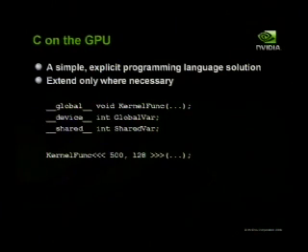As well as running, can you copy between the local memories? No, so the collection of threads that share the on-chip memory are resident in the machine at the same time, but they're not allowed to communicate with others. So we still restrict you on that sort of thread block granularity. That is still a restriction. The reason for that is we don't guarantee which order the collections of threads are issued in the machine at any one time, because we may add more or fewer processors, or just execute them potentially out of order. So we still try to make the architecture scalable in that sense.